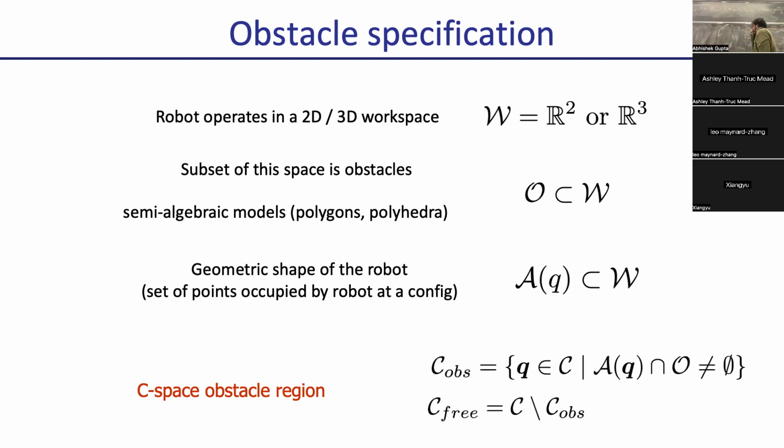So what you need to figure out is, how do I take an obstacle, let's say I have an obstacle here, and map it into configuration space, so that the mapping of the obstacle into configuration space represents all points where something in the body is in contact with the obstacle, right?